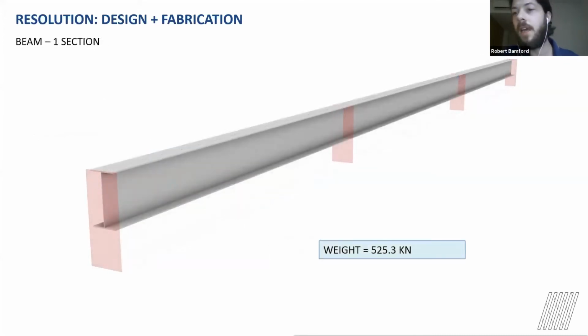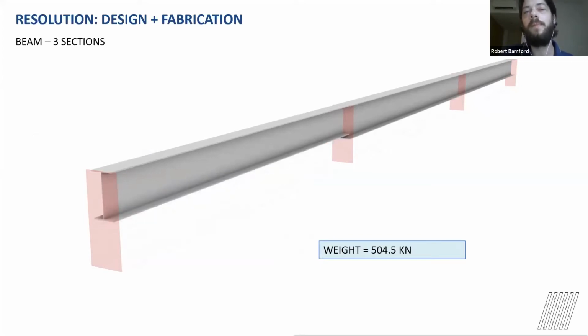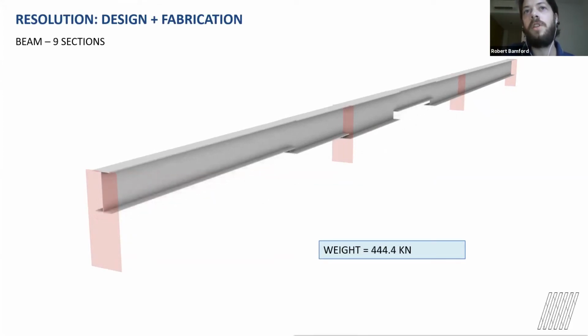So this would then give us, say, the right size. Except, in terms of resolution and scale, this solution only applies at one specific point to the actual problem, at that position of maximum stress. So by looking in more detail, increasing the resolution of the design, and now looking at 3 separate sections, 1 for each span, we find we can tailor the section to each span and reduce the tonnage accordingly.